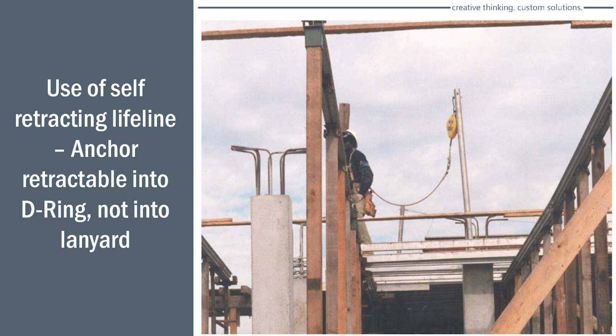Because the way that's set up right there, look at your fall distance. If you got a 6-foot lanyard, you've got that distance you could possibly fall. Plus, you got approximately 2 feet from the SRL. So you've exceeded your 6-foot maximum.